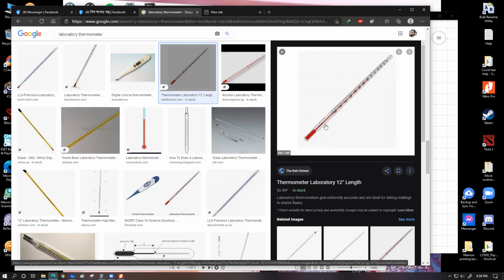Because you have to understand, pure alcohol gives us linear behavior, which is good. If you add some impurities, because that color is not alcohol, so it's basically an impurity in terms of alcohol, there is a possibility that the linear behavior of the thermometric property might be convoluted, destroyed, or hampered. We don't do that. We choose the color, and we also add a certain amount, so that the property is still intact for the workable range of this thermometer. Workable range in this case is -20 to 120.